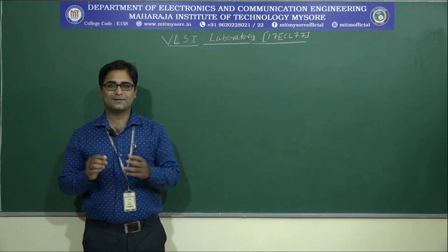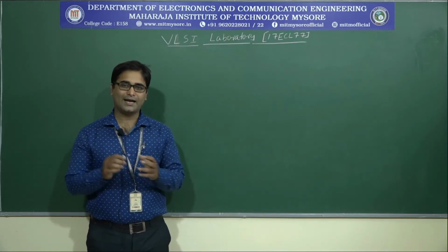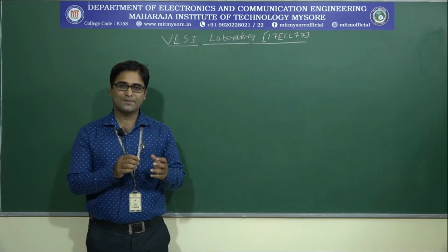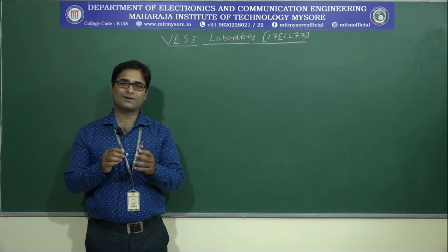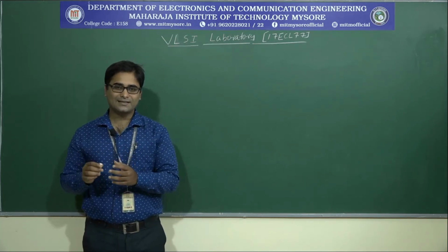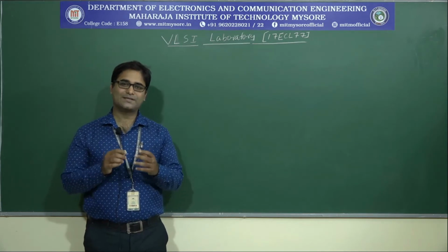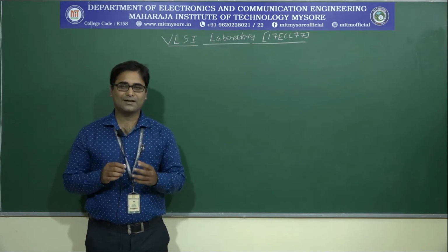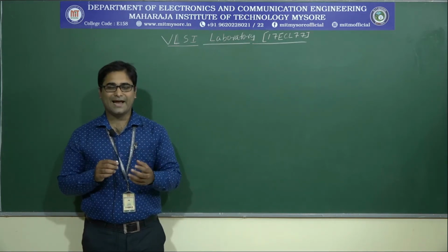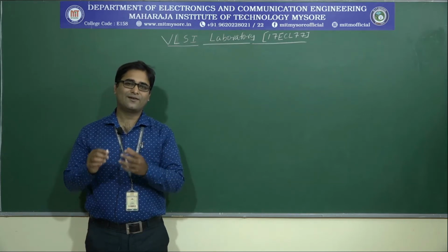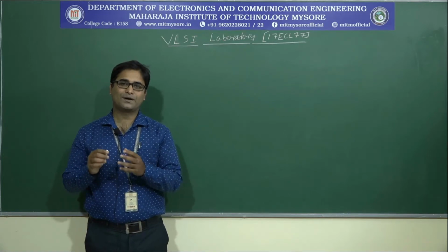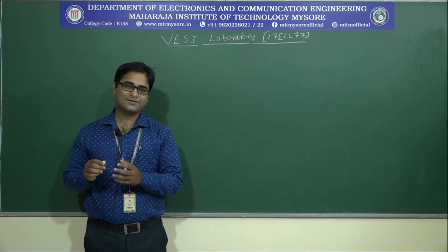The course syllabus is divided into part A and part B. In part A, we have the digital circuits, and the simulation tool for designing the digital circuits is Xilinx. The experiments are how to design an inverter, a buffer, a transmission gate, basic and universal gates, and flip-flops: SR flip-flop, JK flip-flop, D flip-flop, T flip-flop, and master-slave JK flip-flop.